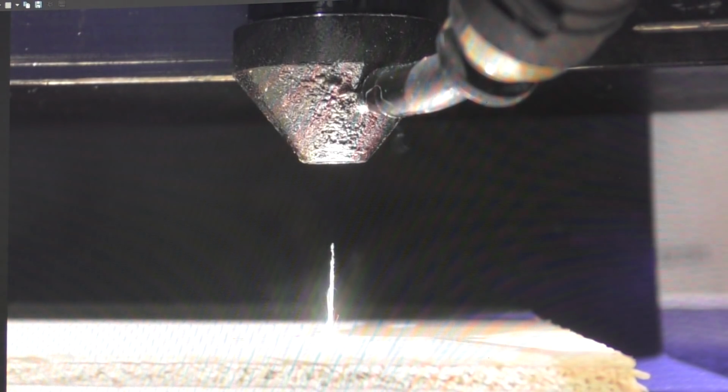Okay, so now I'm going to do a cut with the same power but away from the camera so that we can see what happens. And again, you'll notice we're getting air blown everywhere sideways. But if you look carefully, you'll see that there isn't much happening out this side, but a lot of the air is blowing out this way. We've got some sort of bias happening. Maybe it's because of this air assist direction here, but we've definitely got a bias to the left with this smoke if you watch. Can you see that puff of smoke going out left? Virtually nothing coming out here to the right.